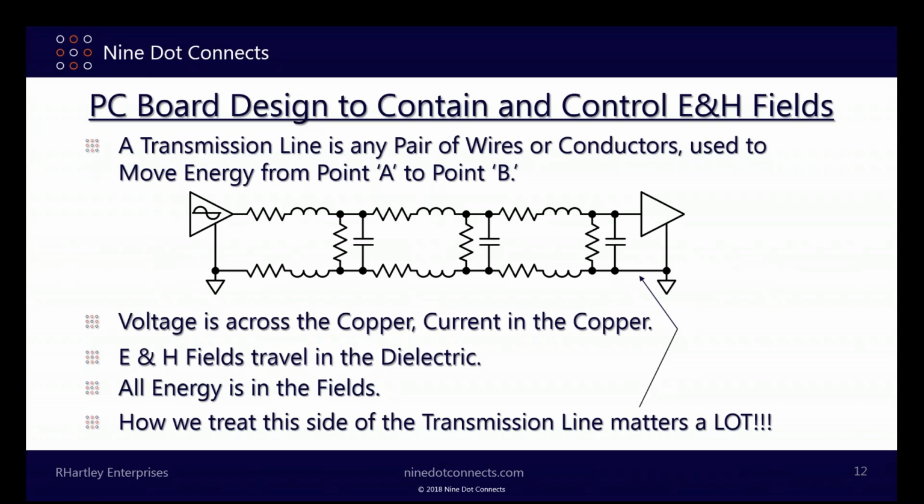And this creates discontinuities that cause field spread and can lead to serious EMI problems. It won't create a signal integrity problem because the energy will find a path back. It's just that the path it finds will be ugly and you won't like it. It'll create noise, and it probably won't create enough noise to cause a signal integrity problem. But I can tell you from past experience, it will create more than enough energy spread to cause EMI problems. So be careful. So what can it be?